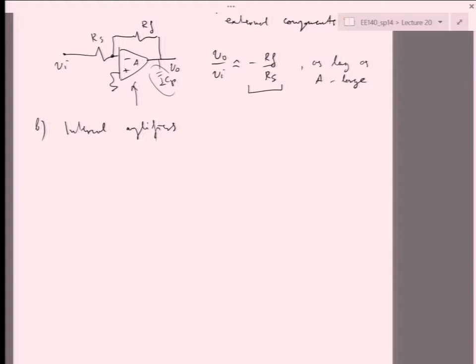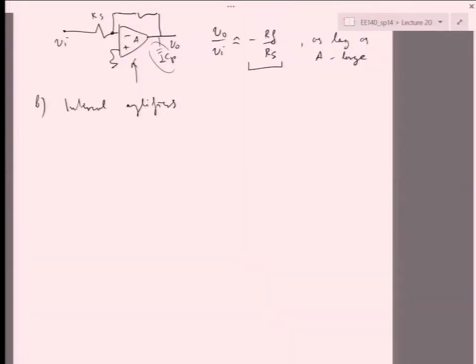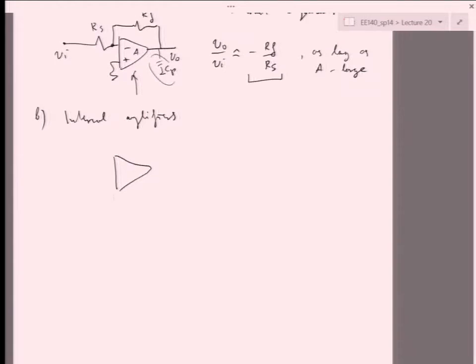So you can relax some of these constraints in order to improve performance and really push the edge on the performance or power of that amplifier. For example, in an integrated process, I would not necessarily use a resistor because it's very imprecise. With polysilicon resistors, the error is plus or minus 10, 15, sometimes 20%. That's a pretty large error in the gain that I don't necessarily want to tolerate.